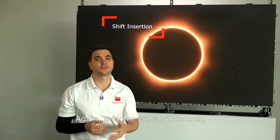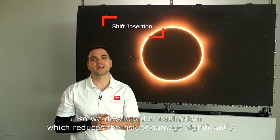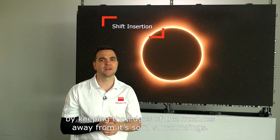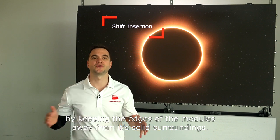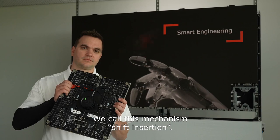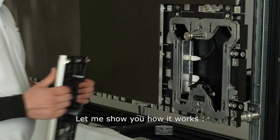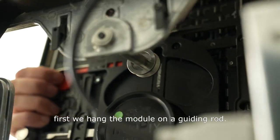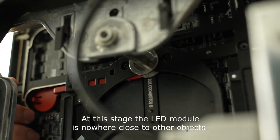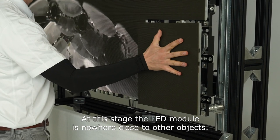Again, a factor we cannot control, so we developed a mechanism which reduces the risk of damage significantly by keeping the edges of the modules away from its solid surroundings. We call this mechanism shift insertion. Let me show you how it works. First, we hang the module on a guiding rod. At this stage, the LED module is nowhere close to other objects.